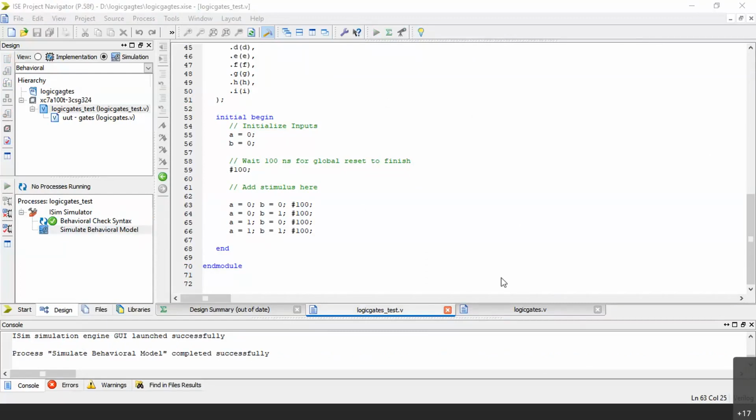Now you can see that it has executed only once until the stipulated time period that is there in the test bench. It has remained like that till 1000 nanoseconds. Here you can see it has remained 1, which corresponds to the code there. So that way initial is going to help us. We can move this cursor wherever we want, and accordingly we can check the values.